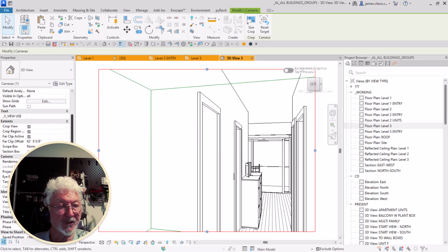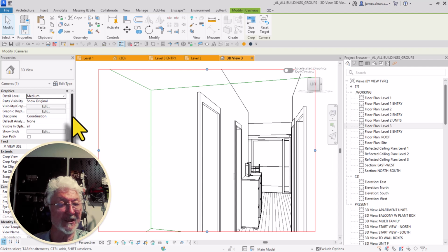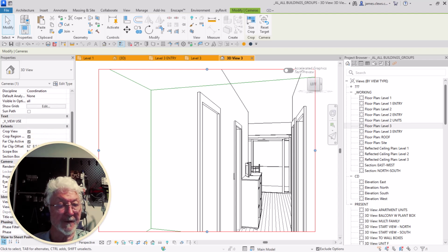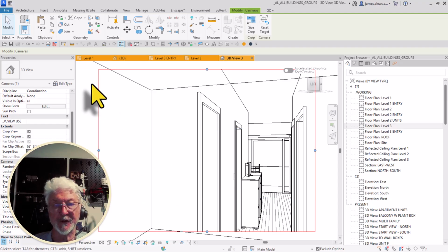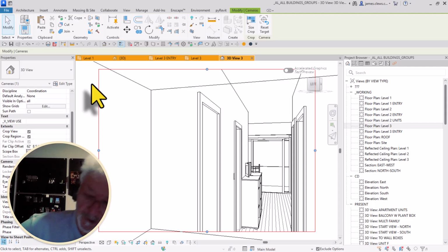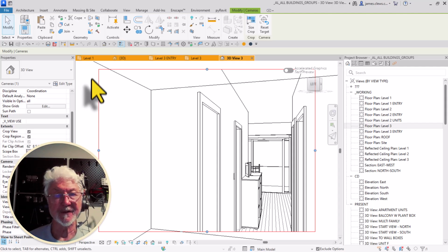And when you're using a scope box, down here for example, where I say the scope box is just that of unit F, this means that I'm only loading the geometry that's in this particular area, not my entire project, not all of the 3-story high multifamily unit.